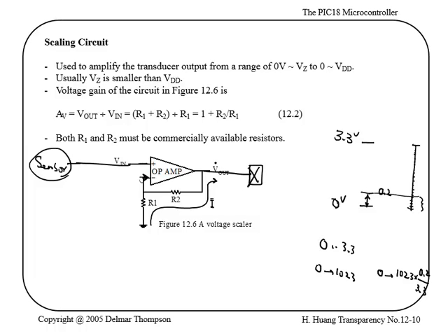Now, if you look at your V out, you basically have a voltage divider circuit, right? The voltage here is going to be the same as your Vn, right? So if you have the same current going through that, you're basically going to first solve the equation up to here. So basically your I R1 is going to be Vn. Solve for I. That means I is going to be Vn divided by R1.